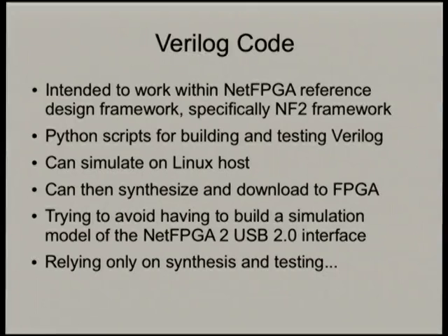The Verilog code is intended to work within the NetFPGA reference design framework, specifically the NF2, the NetFPGA 2 framework. It uses Python scripts for building and testing the Verilog, and can simulate on a Linux host, so all their development was done on Fedora-based devices, and they have a complete simulation environment there. But it's again using proprietary Xilinx tools which do run on Linux. And then they have a synthesize environment to download the code across PCI onto the FPGA on the NetFPGA card.